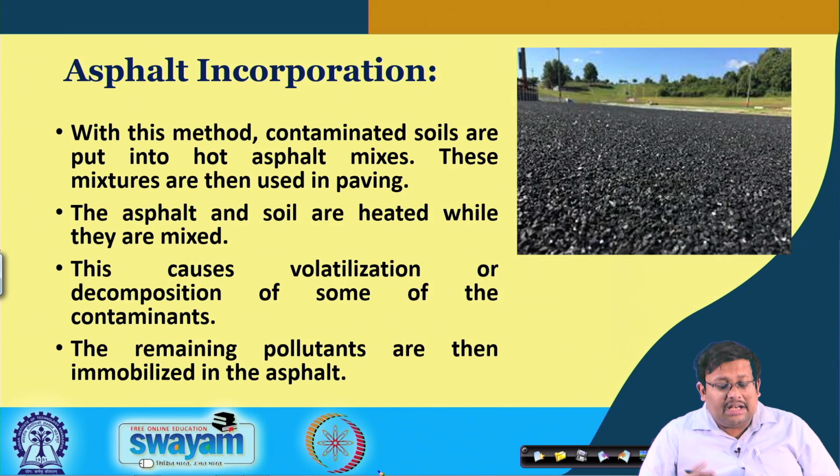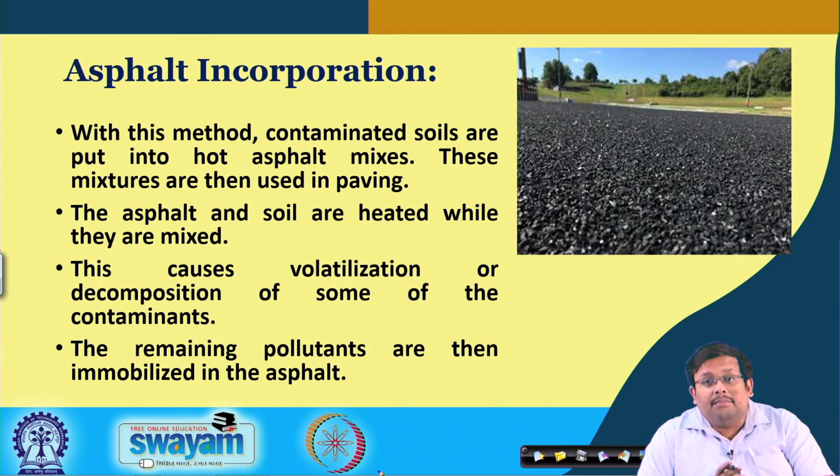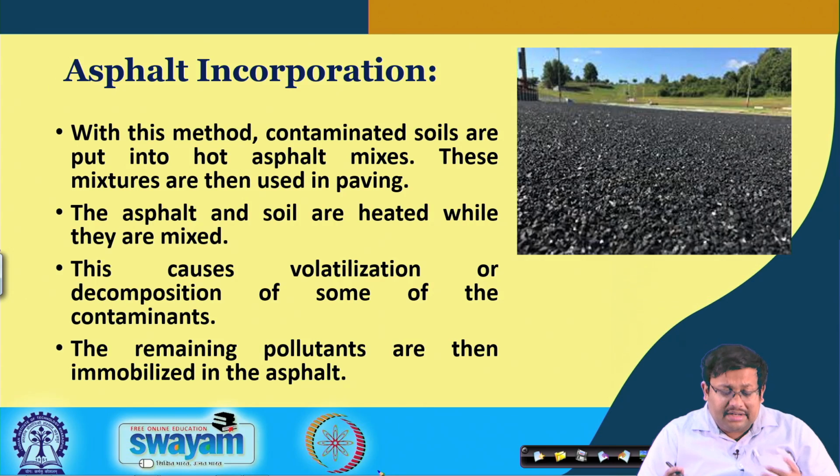While mixing the soil with the hot asphalt, it causes volatilization or decomposition of some of the components, and the remaining pollutants are then immobilized in the asphalt, which is a beneficial effect of this asphalt incorporation. So, this is a very important method for ground treatment or soil treatment in urban areas,